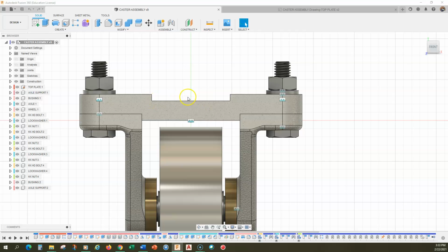It's not really critical. Why do we have that little notch in there? Well, it's to provide a surface here and a surface here so that we have maybe 2 flat surfaces, to give some kind of relief. Maybe it's going to be on a rail, the left and right rail, and there's nothing in the middle, or there's something in the middle that would cause this to sit wrong.